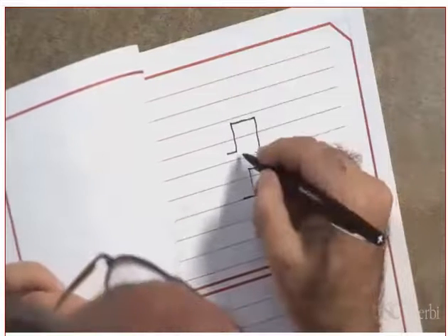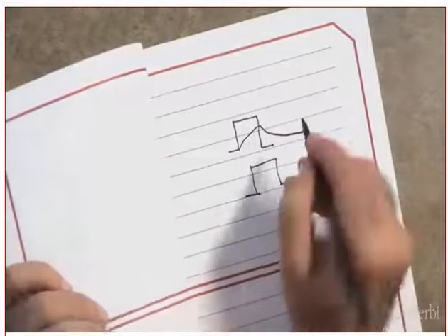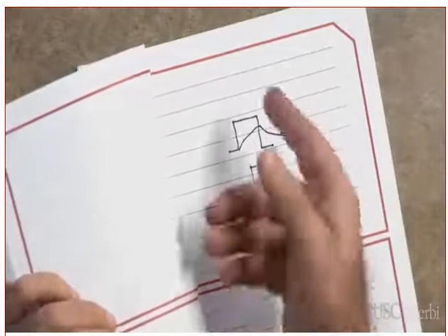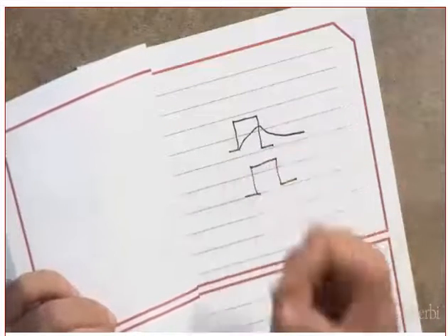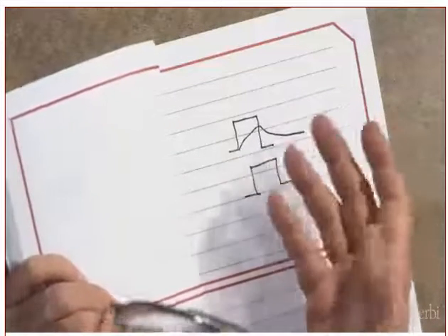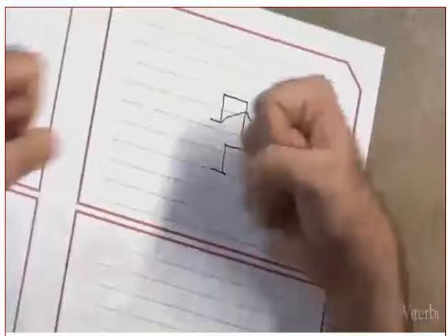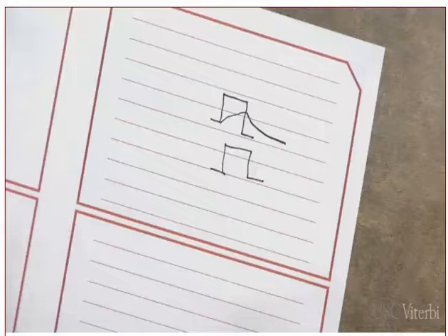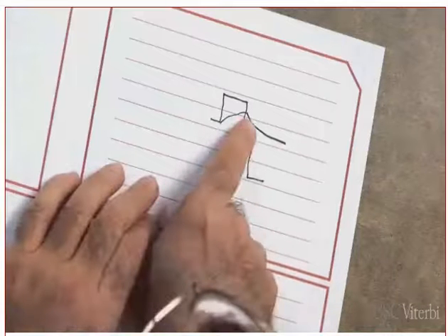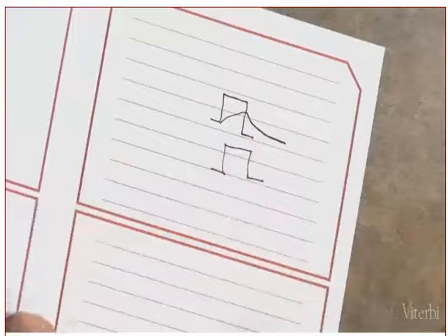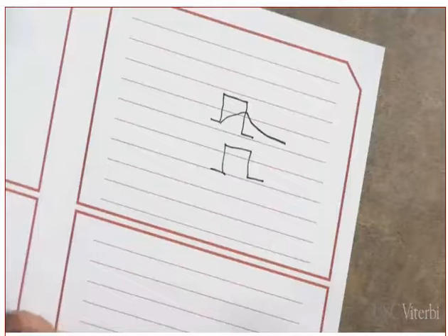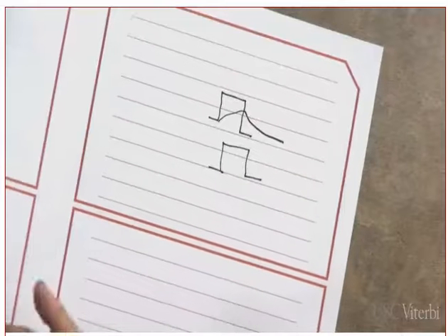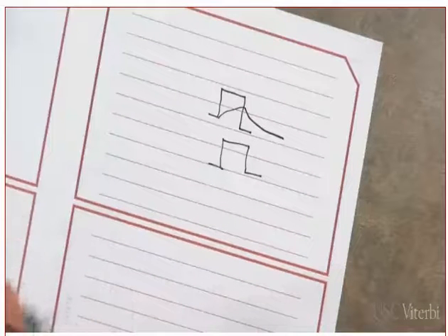However, if I get something like this, was there phase distortion? There was phase distortion. What does that mean? The pulse gets smeared. Do you understand what smear means? It's as if one is pushing the pulse this side, the other is pushing it the other side. Now you might say, so what's the big deal? The big deal is that this decay will interfere with the next symbol, which is referred to as intersymbol interference.